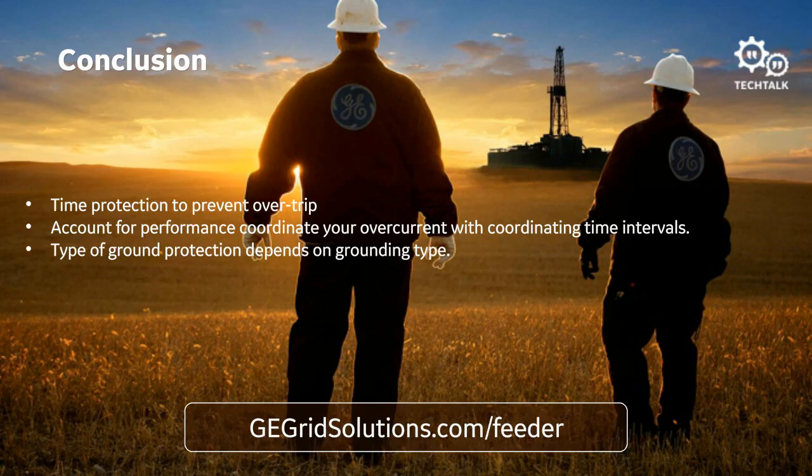So let me conclude so we've got some time for questions. For overcurrent protection, we need to time coordinate those devices so that we don't overtrip. When we are coordinating devices, we need to account for the performance of our devices with our coordinating time interval. And lastly, I spent some time on ground protection, and the type of ground protection depends on your grounding type. With that said, I think we have some time for questions.